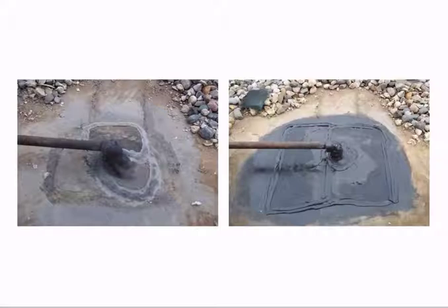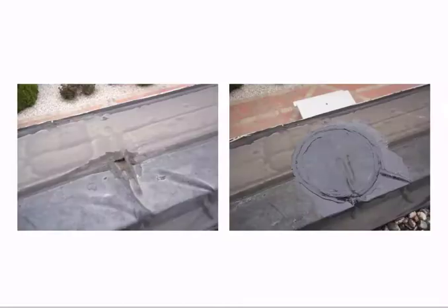So the picture on the right does show a real nice clean patch. Looks like they did a nice tight field wrap to that gas line, and then a two-piece target over that, with the proper sealant around the edges. And you can see the primer that was installed. So job well done on that one.